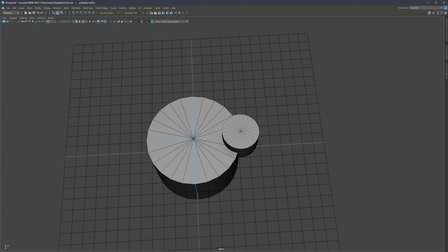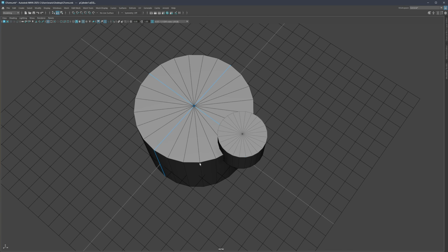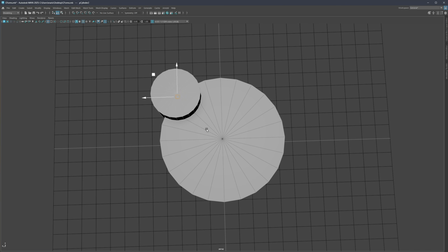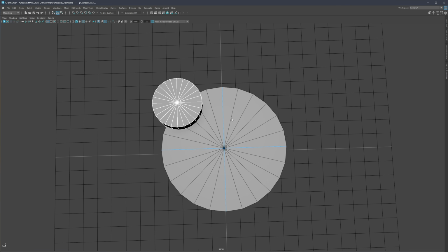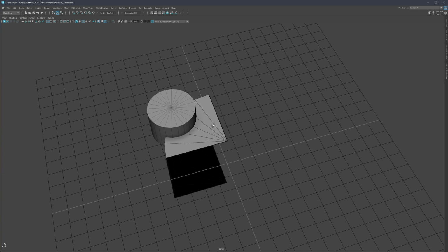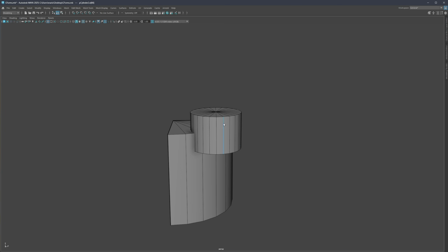So the middle is going to be here, and that means that this cylinder needs to come to this corner right here. So it needs to be here. Also, the cylinder sides are set in intervals of 4 for the reason that we can always separate that 1/4 and delete the rest, so we can work on just one piece, and then simply mirror it to everywhere else we need.